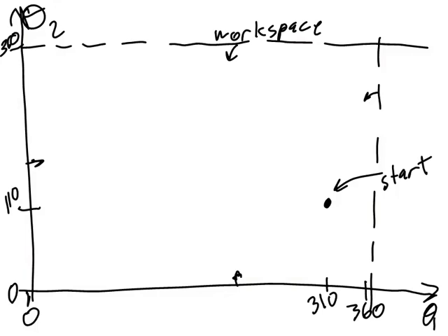Back here in configuration space, I'm going to mark this point as start point 1. That's the first possibility for how to place the end effector at the start location. The second option is at theta 1 equals 45 and theta 2 equals 270. I'm going to mark this point as start 2.